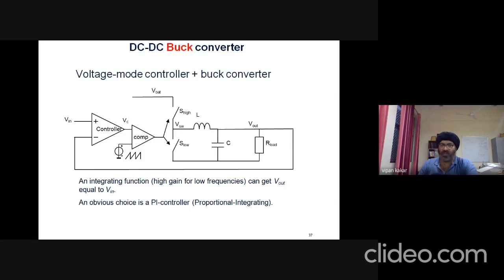A new compared voltage is received over here, which is in terms of pulse width, meaning a new turn on and turn off time is received at the output of the comparator, which is again used to switch on and off these devices at a different switching frequency. So the switching time keeps on changing based on the output fed back at the input. Because this input is fixed and the sawtooth is fixed, this output keeps on changing. And when this output is equal to this input after some iterations, this pulse width will remain the same.